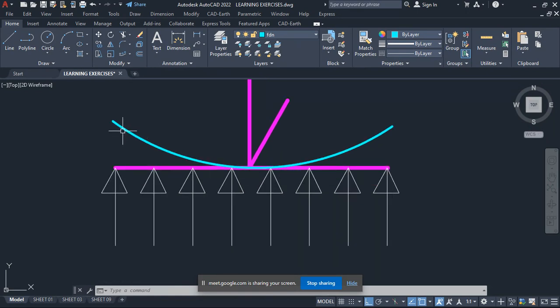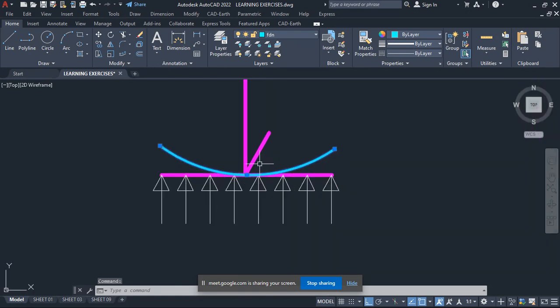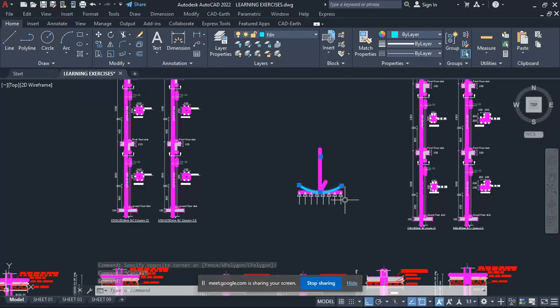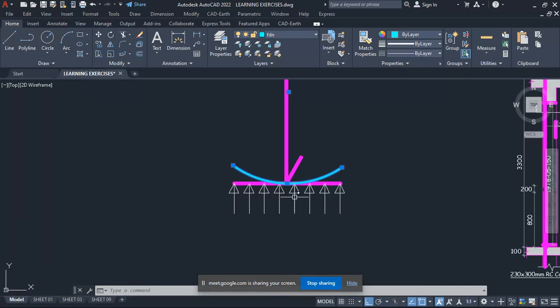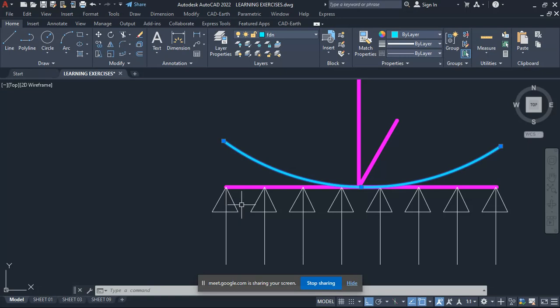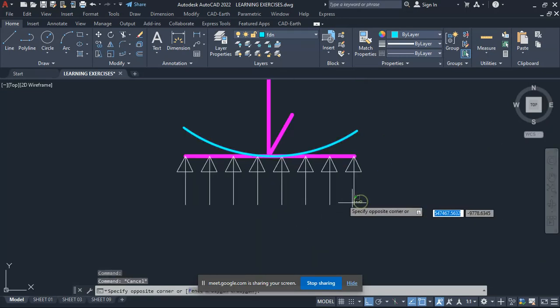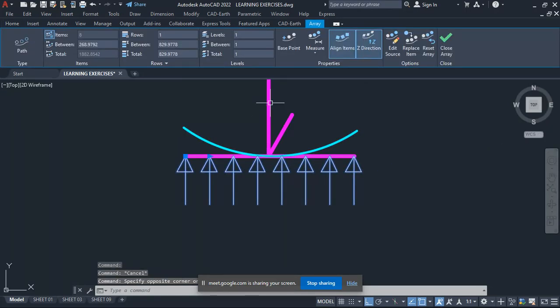So now we have to design. When you apply this actual load and already there is something saying don't push me, this is soil here, the base will be forced to bend in this direction. Now we design for this bending. If you're doing a manual calculation, according to the bearing capacity here and the actual load, you can actually get this moment.